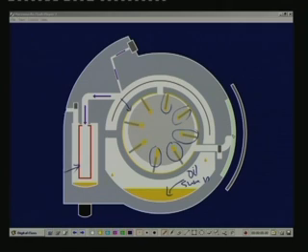Okay. So refrigerant vapor enters like this, it gets compressed, it comes out like this and flows out like this, and this, as I said, is the oil separator. Here oil gets separated and only refrigerant vapor will go on, and this separated oil will again come back to the oil sump through the oil return valve.